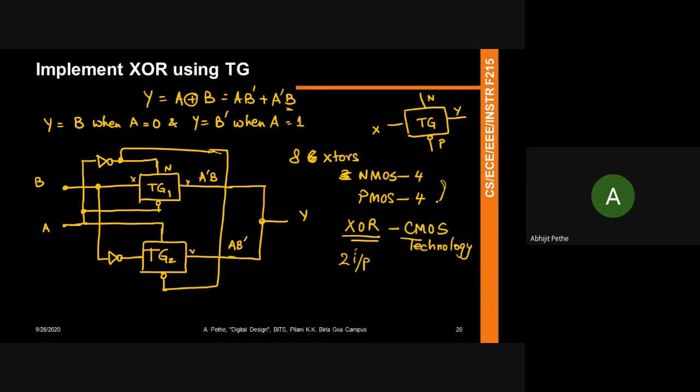Okay. Gaurav asks, how do we differentiate between high impedance and low as the output will be? No, Gaurav, I was trying to answer the same question to Ramnathan. 0 and high impedance are very different, right? When you say something is a 0, you know the voltage is a 0, there is some current coming out of that gate. Remember VIL, IIL and IOL, right? There are currents flowing through those gates. Now, when you have a high impedance, there is no current. So high impedance and low are not the same. That's why I taught you digital logic families. High impedance is very different from a low. In a low, current is flowing. In high impedance, there is no current flowing.